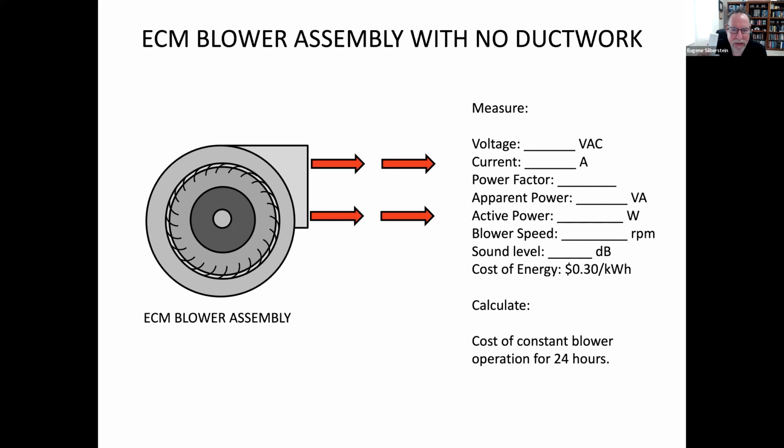All right, the meter that I showed you before measures sound levels between 30 and 130 decibels. Your target for an air handler should be about 20 decibels. Just for point of reference, normal conversation is typically between 40 and 60 decibels. A condensing unit, about 50 decibels. And once you get above 70, then that's when you could start to get damage to your ears.